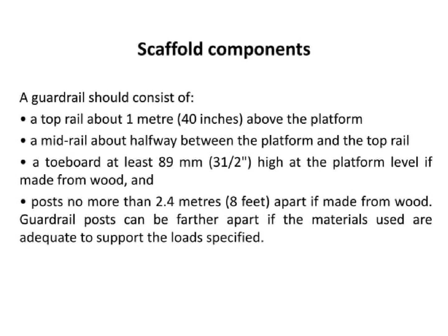The toe board should have a minimum height of 89 mm, 3-1/2 inches, if constructed from wood, while posts should be 8 feet apart or less. Different materials may allow for different post spacing, as long as they can support the specified loads.